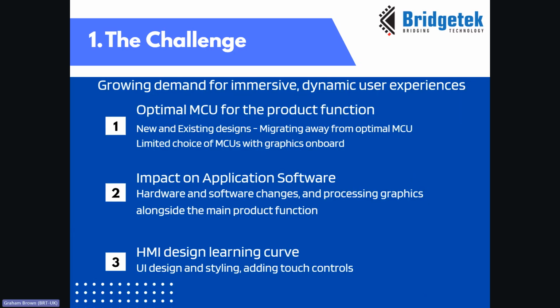Adding the graphical user interface brings a new set of requirements which go beyond the main product functionality. If we move to an MCU with graphics on board, we risk moving away from the most optimal and economic MCU. We risk extensive rework on the hardware, on the firmware routines, and learning new MCU tools, and even the learning curve in designing graphical user interfaces if our design team are inexperienced in this area.